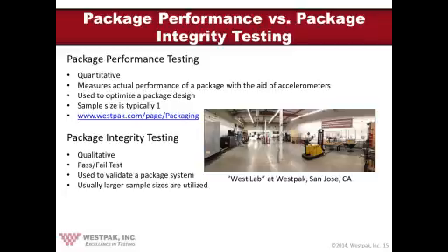Again, a performance test is quantitative. In other words, numbers. You've got to have numbers for a package performance test. One of the reasons for that, obviously, is to determine pass or fail criteria. But if you know that you pass by a wide margin, because you have the numbers, then you don't really need a large sample size. For example, if the fragility of your product is 80 Gs and the package transmits no more than 40 Gs, you've got 100% headspace. So you know that going in. But you only know it if you do a performance test where you're actually getting quantitative data. In other words, you get the numbers out of the whole thing.